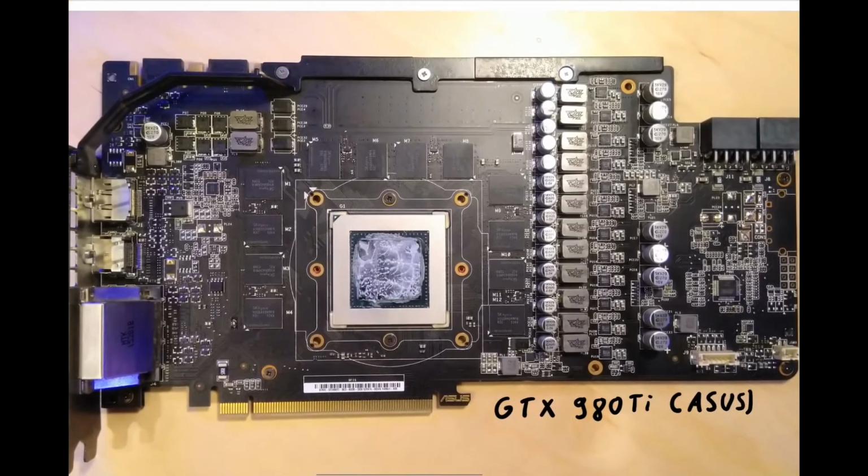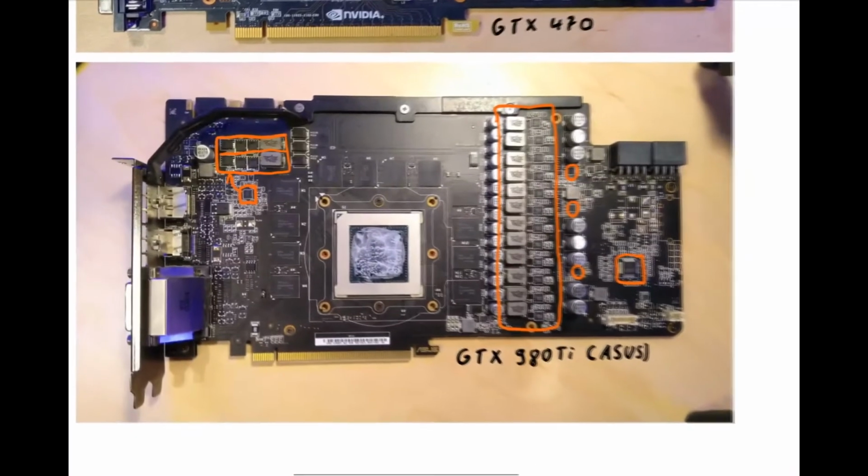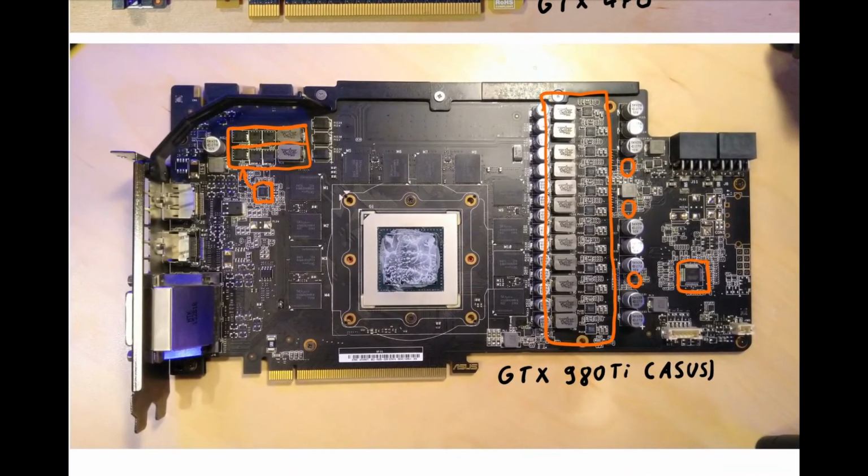So again, here we have our card with the doubler VRM. Here we would count 12 inductors, but it's actually a 6-phase because we have these chips right here which are doublers. And if this wouldn't be an ASUS card, we could also look up the PWM controller, how many PWM signals it supports, and then find out it's only a 6-phase PWM controller. Then over here we have VMem. These are 2 phases, and that's also the PWM controller for VMem. This one you can actually look up, because ASUS generally doesn't rebrand VMem PWM controllers, only vCore. So you can also find out that this is a 2-phase.